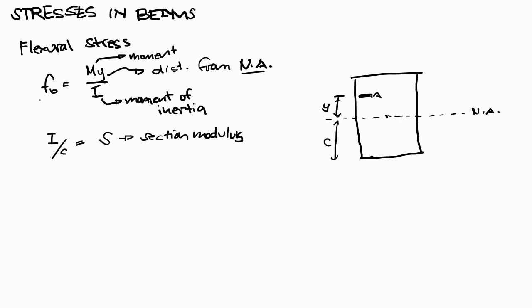Now, pag titignan mo yung flexural formula, ang sinasabi lang nito, diba, ang maximum bending natin would be Mc over I. Now, kung papalitan mo to ng S, this would be equal to M over S. So, yung maximum bending natin, let's label it as f_b max para hindi tayo ma-confuse. The maximum flexural stress or bending stress is M over S, where S is the section modulus.